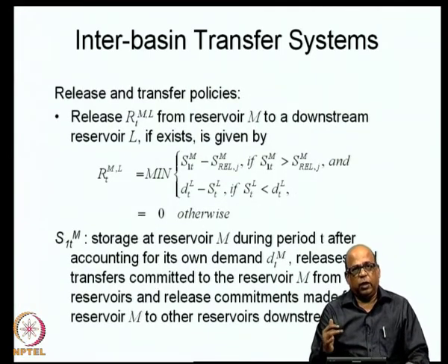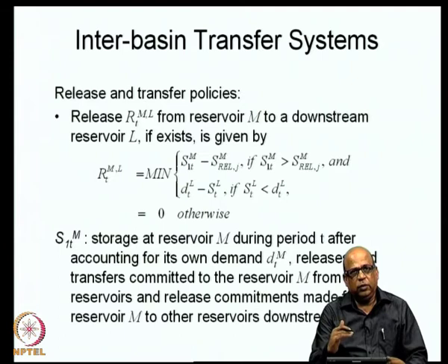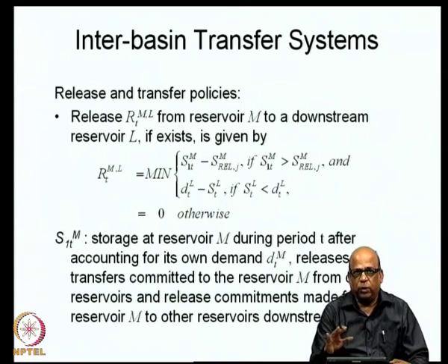We will now define the release and the transfer policies. First, meeting its own demand, there is no policy. If water is available, simply meet the demand. There is no policy, that is a standard operating policy. You look at any particular time period, if there is a certain demand and you have water to meet that demand at that particular reservoir, simply meet it. Do not look at other reservoirs, do not look at other time periods, do not look at other basins. That is a diversion policy.